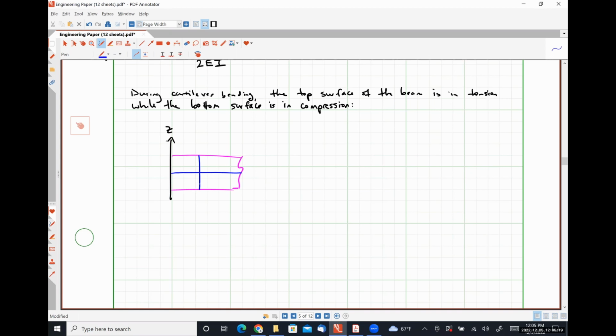And what we will find is that we have tensile stress up here, compressive stress down at the bottom half of the beam, where we're assuming that beam deflection was in the down direction here, and that these completely cancel each other out. Our stress is 0 along that horizontal axis of symmetry.